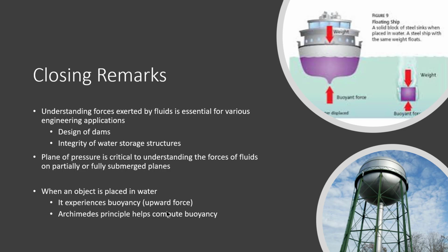So in today's lab, we're going to show that the moment is proportional to the height of the water in case of a fully submerged surface, and the moment, or a function of that moment, is proportional to the cube of the water height in case of a partially submerged surface. So that's what you will experimentally determine in this lab.